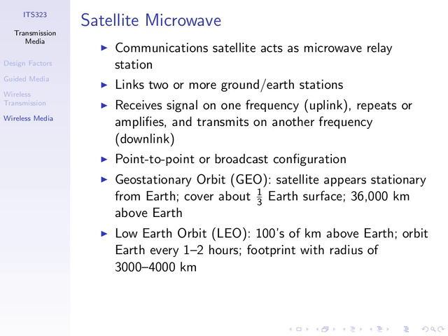And in fact, for the signal sent on the uplink and downlink, usually so we can communicate in both directions at the same time, we use different frequencies. So one frequency for uplink and one for downlink. And what the satellite does is relay that signal. As you transmit up to the satellite, it's an amplifier or repeater. It just sends the signal down to the receiving ground station.